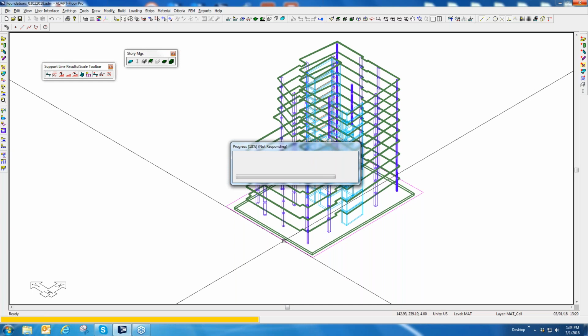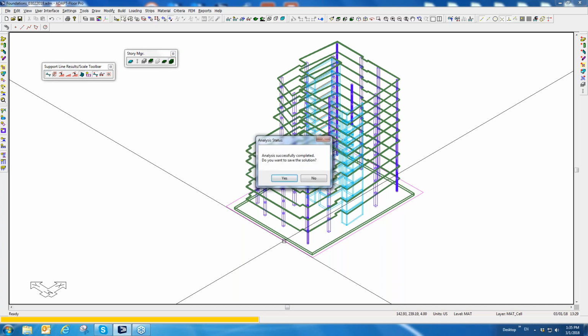But for lateral, for wind and earthquake load cases, you might apply a value that's lower than that. So you can combine solutions that stem from different stiffness cases into the same rerun of those reactions. That might be a reason why you would want to use multiple usage cases.